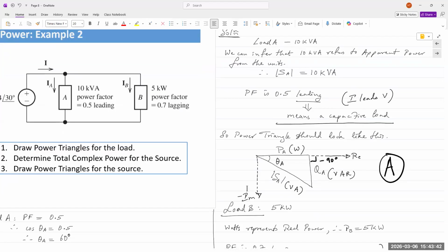Okay, to logically approach such problems for AC power, where we are trying to determine the power triangle. Again, power triangle, P, Q, magnitude of S, and the power angle theta. Those are the 4 quantities. We are provided with 2 of those. We can calculate the other 2.